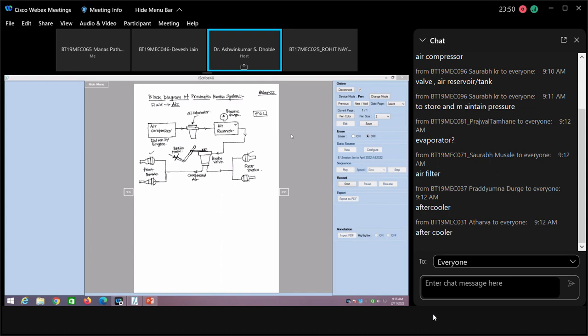You can have a little lubrication if required in the circuit, otherwise you need to filter out the oil droplets from the air and allow the air to be deposited in the air reservoir under some pressure P. Suppose you run the vehicle and park it, then when you start the vehicle again, the compressor will generate air under pressure, it will get filtered, then move to the circuit. By that time the required pressure may not be reached, and the brakes may not work initially if there is no air reservoir.